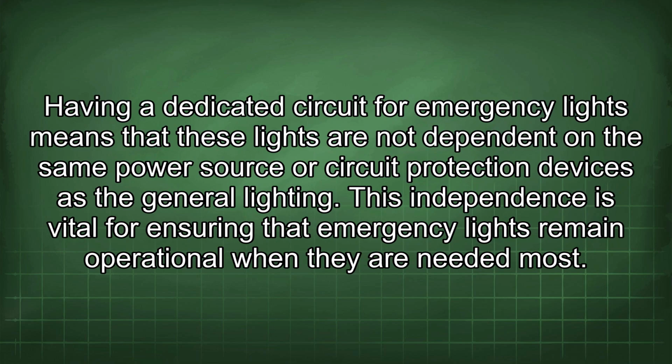Having a dedicated circuit for emergency lights means that these lights are not dependent on the same power source or circuit protection devices as the general lighting. This independence is vital for ensuring that emergency lights remain operational when they are needed most.